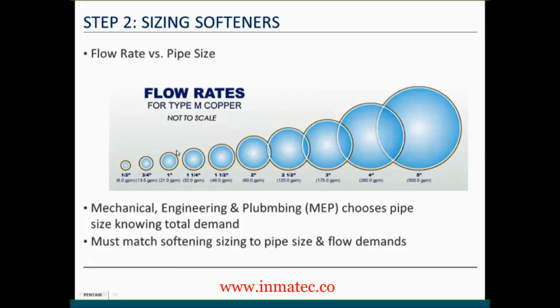That 1-inch softener is going to go through this line. Doesn't matter how big it is back here. It could be 3 feet. You will still not get any more out of that softener than 21 gallons per minute.